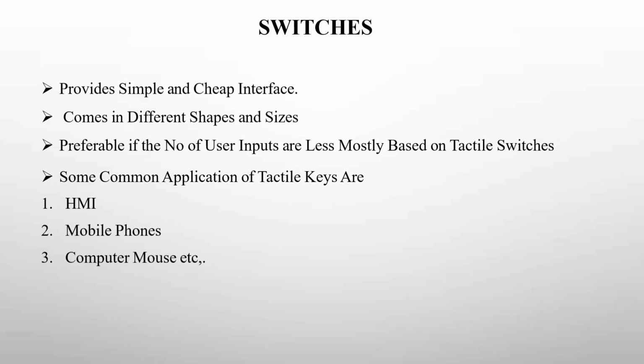And coming to switches, a switch is a simple input device used to open or close a circuit in embedded systems. Switches are often used to collect user input, such as selecting cooking modes or entering cooking times, like that. And most commonly used switch is tactile switch. The most common applications of tactile switch is mobile phones, computer mouses, etc.